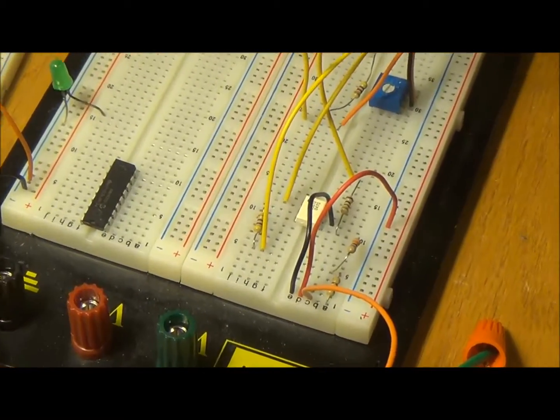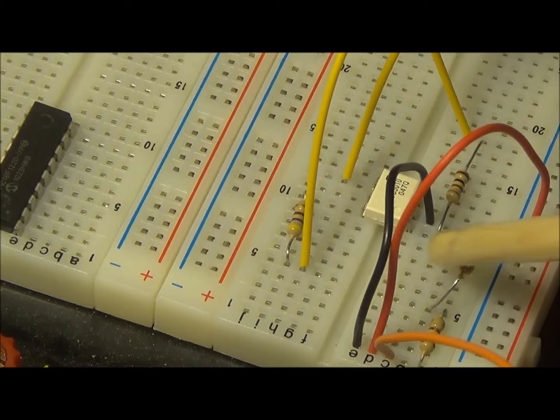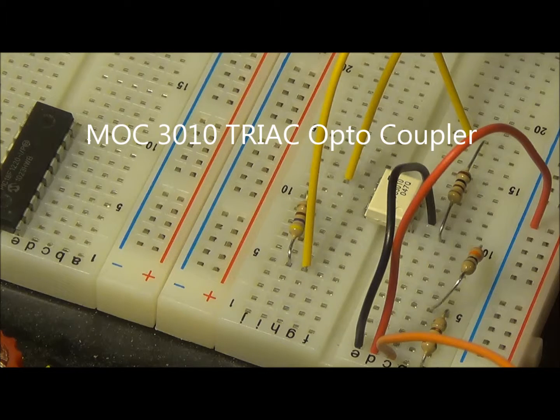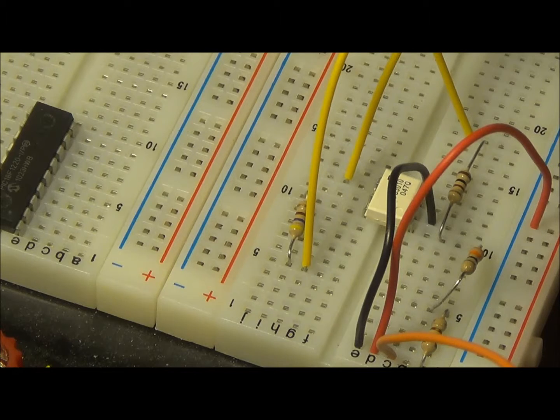I don't take this directly to the Raspberry Pi controller. Instead, I'm using some optical isolation. The reason for doing this is safety, because I want to have the high and the low voltage sides separated. On the optocoupler, this is the input side and that's the output side. I have the control signal coming from Raspberry Pi here.